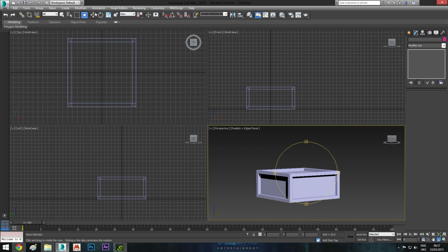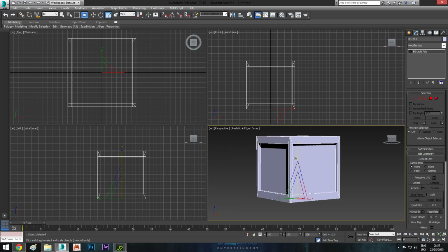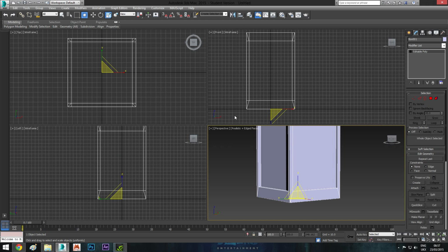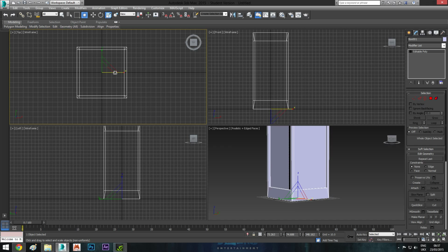But we want to save space, so we want to make this thin and tall. So how do we do that? We just click the geometry that we've created, left click, that's the entire thing, and now we go to select and uniform scale, and we just grab the Z axis and bring that up. Then we click on our top frame and use Y and X just to minimize that down a bit, make it a nice square, a nice healthy square. Okay, so select and move.